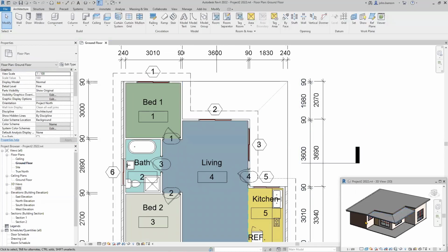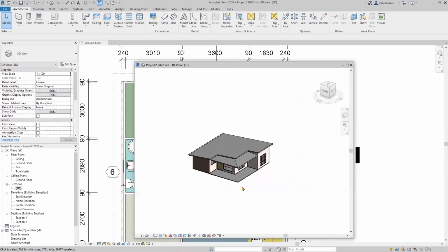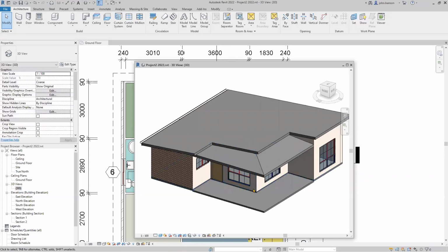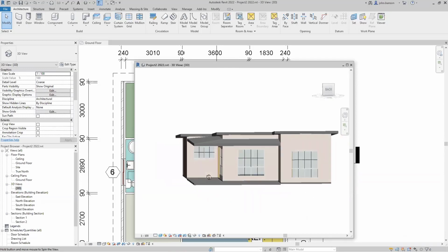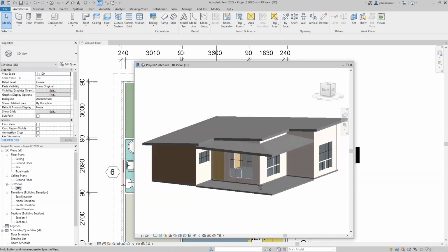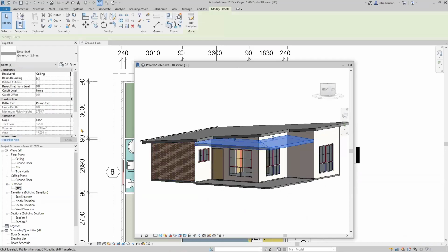The roof is now on there and you can see it in the 3D. Let's make that bigger for now and double click the mouse wheel and then scroll around. And if anything, I could probably drop that down a little bit so I can select that there now. And in the properties palette, I can drop the base, say 200 mil.